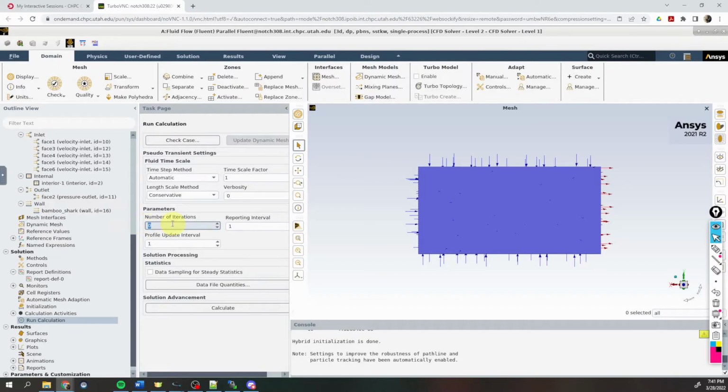We'll use a max number of iterations of 200. Depending on the Reynolds number that we end up with, if our simulation is either in laminar or turbulent flow, these time steps may never converge. So like those residuals that slowly go down, they may never reach a point that will completely stop the simulation. It may go down and start to kind of oscillate a little bit. But after 200 iterations, we should be getting close enough to the real answer that our results will be good enough for what we need.